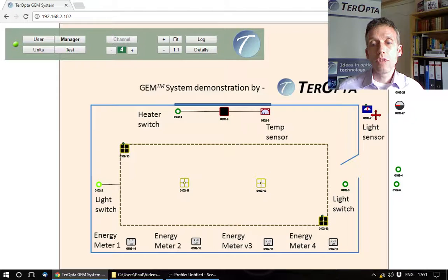If I want to remove the channel, I click on the sensor again. I go on the minus button, reduce down through the numbers until I get a dash, and then just hit the channel button again, and the dots disappear and the virtual connections come back.